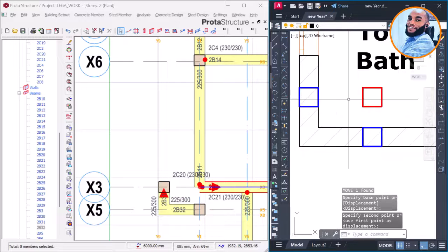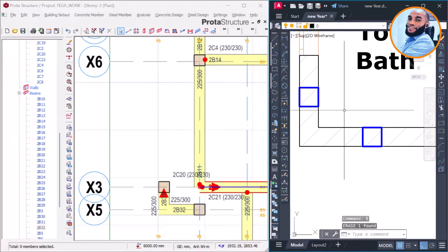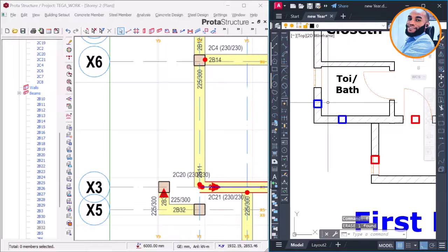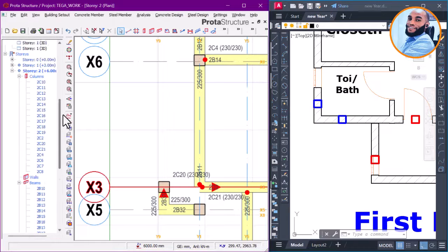That's fine. So this cannot go now because we have now provided what? A support for this edge while we are taking off this column. Okay, that's fine. So while you take off a column, make sure you provide a support. So right now we will now go to what? Plan view. So it's story 1 to go and provide a support under it.